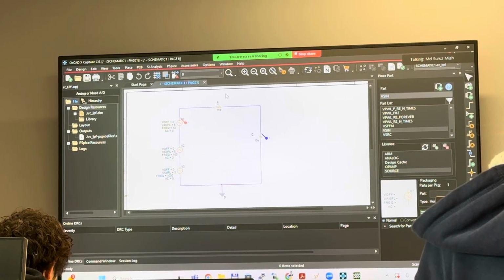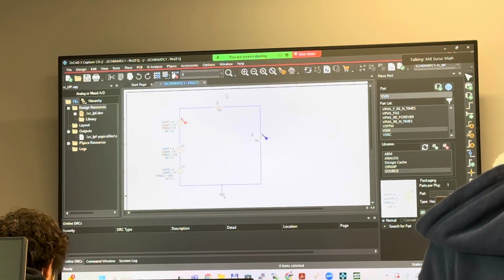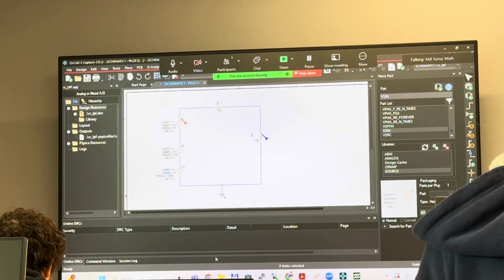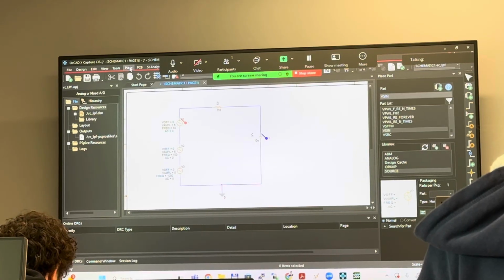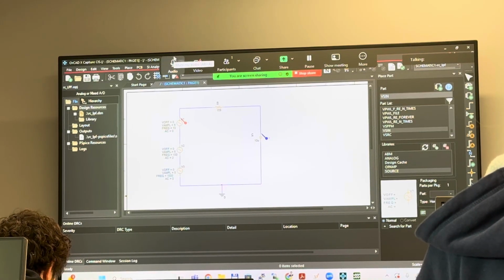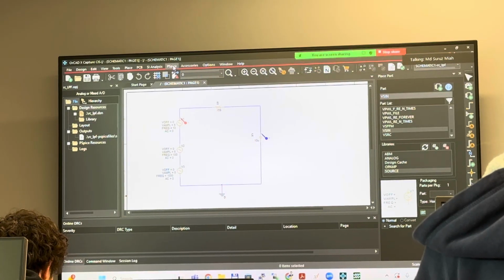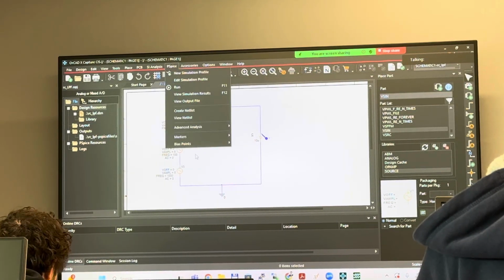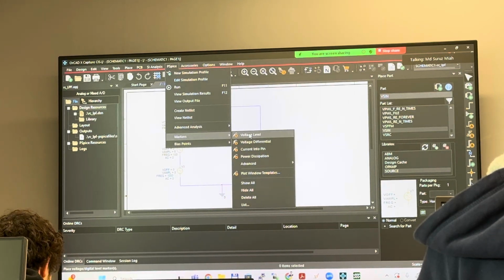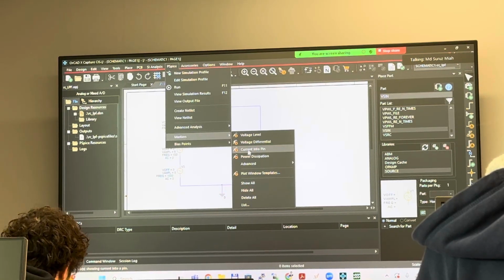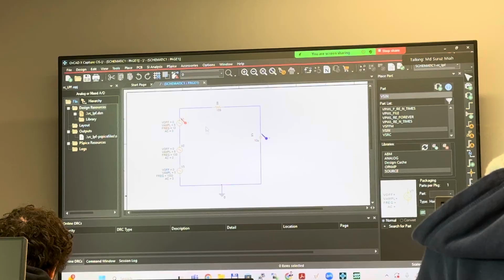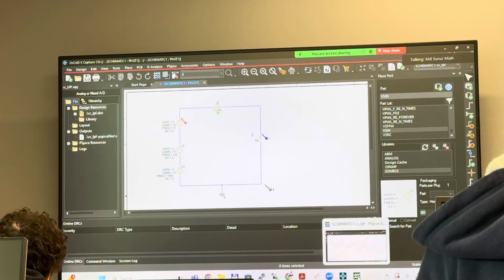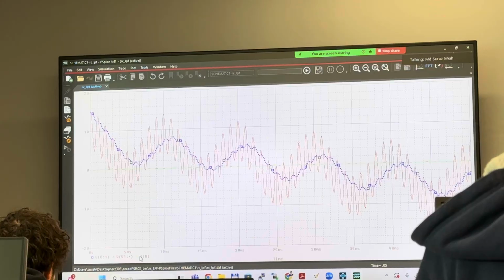You will not see anything, you will see a blank screen. But if you want to see something, you have to use Probe. Okay? You have to use Probe. So this Probe in PSpice basically, it is PSpice, markers, and voltage level. You can actually add current as well. So for example, I want to see how much current is flowing through this resistor. Okay? Immediately you will see, there should be another. Do you see here?